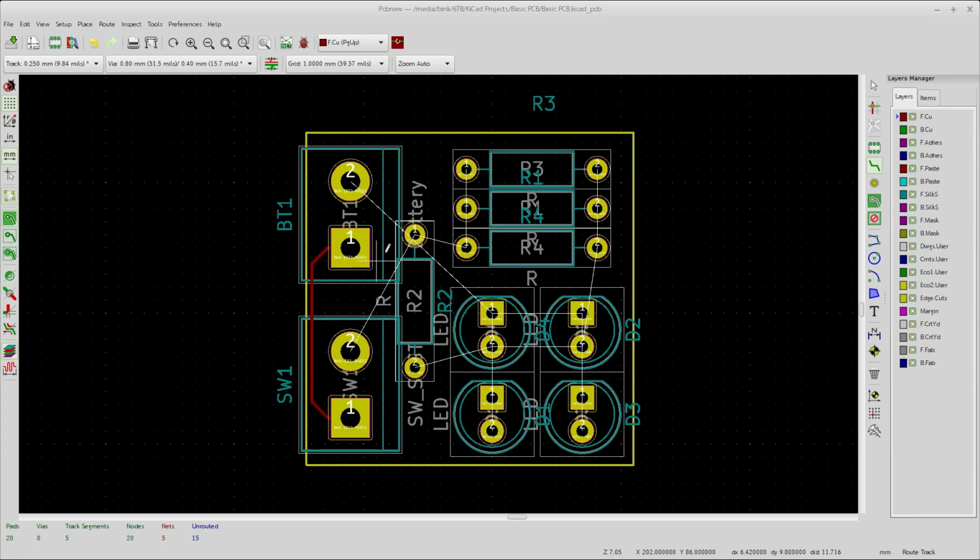Now you see if I run this over here, it's definitely going to cause problems with this getting over to here and this over to here. Something's going to have to give. Now don't start making vias through to the back side right off the bat either. Do your best to stay on the top layer as much as you can so you don't end up screwing yourself over by creating too many traces on the back and the front and creating walls again.